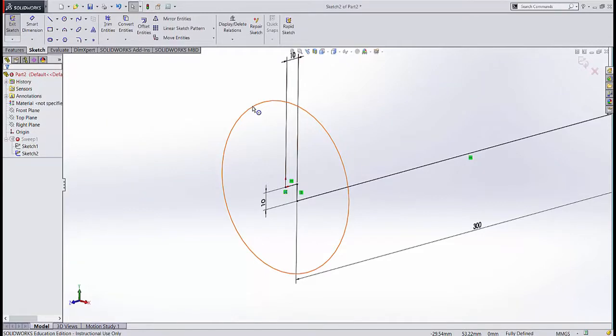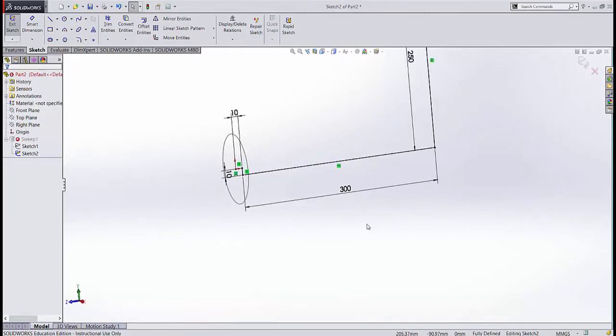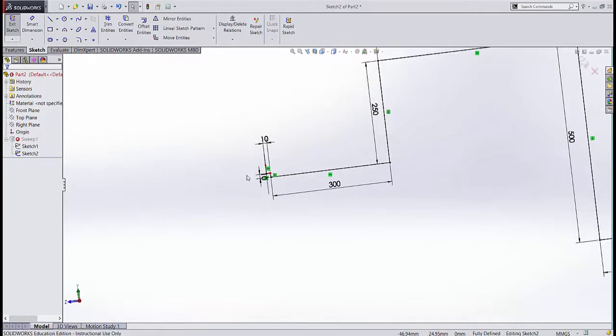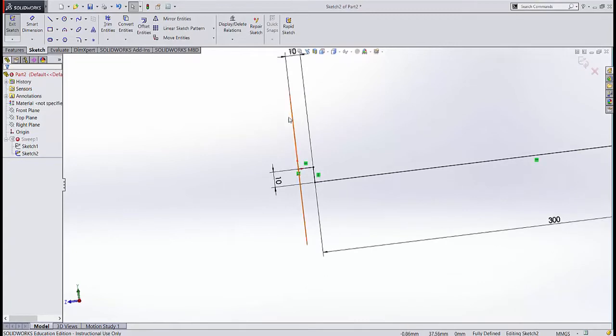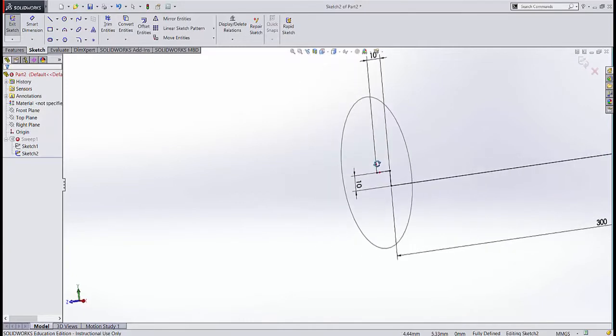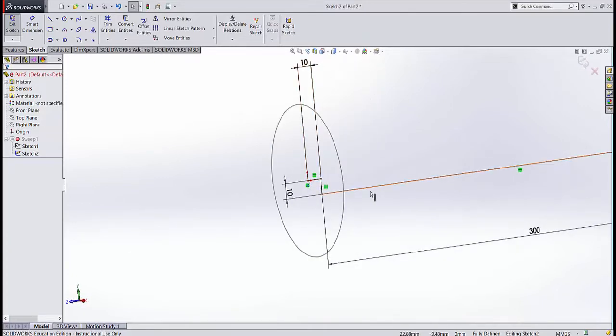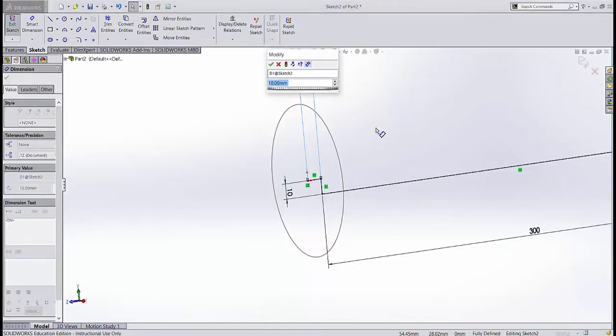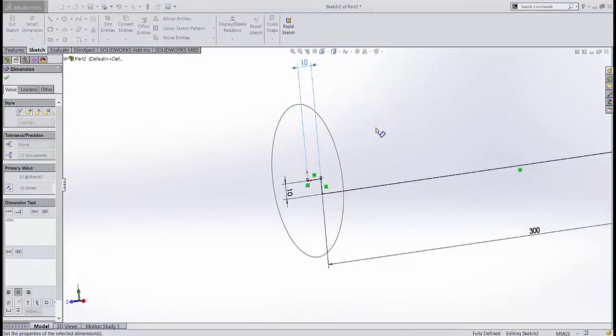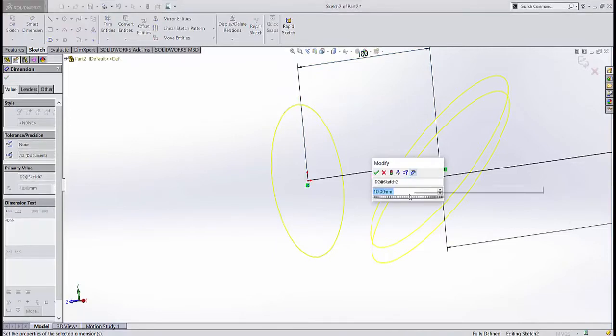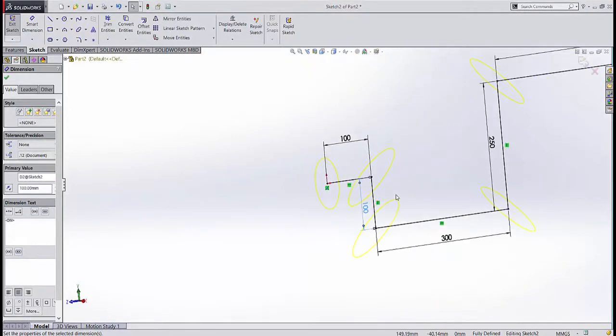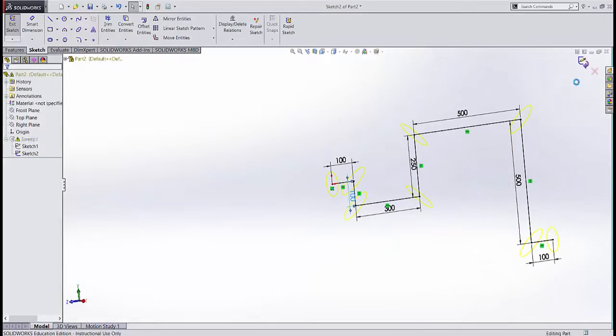The dimension of this circle is 100 millimeters in diameter. If one were to try to take that and negotiate this curve, you'll note that there's self-intersecting geometry here. In other words, the curvature of the path for the sweep should not be very much smaller than the dimension of the profile that needs to be swept. I'll increase these back to about 100 millimeters, which should allow for the sweep path to be resolved.